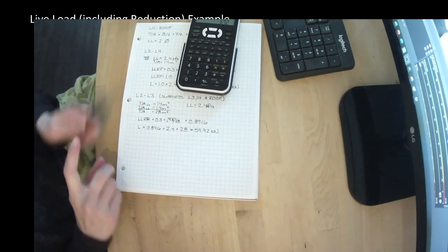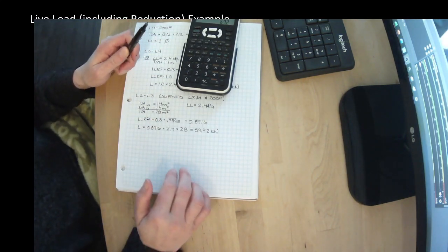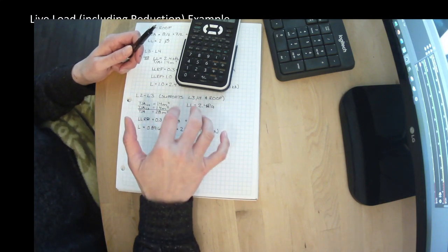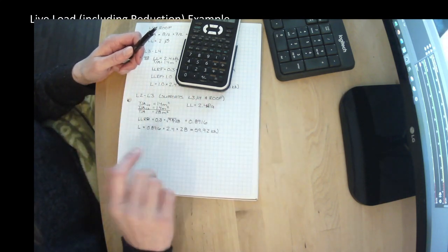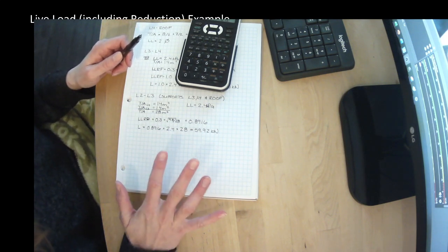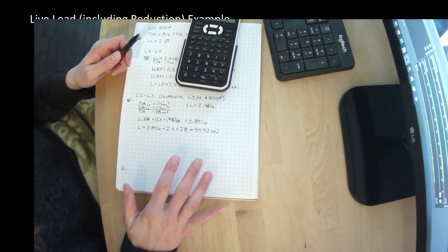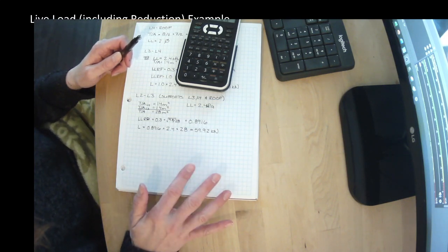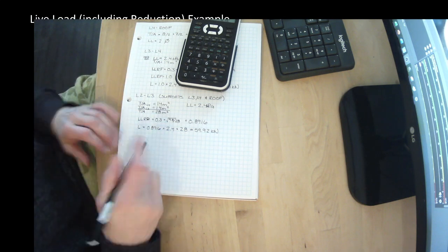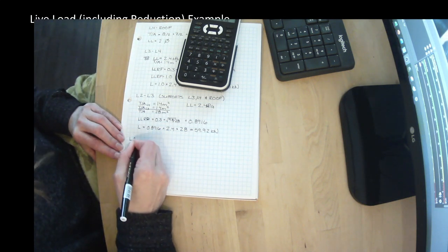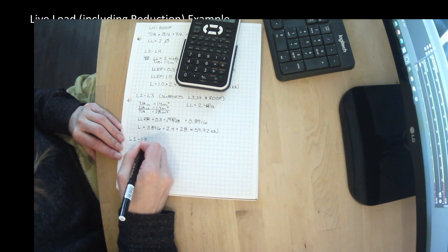What we're saying here is that the odds of both level 3 and level 4 in that zone having full 2.4 kPa live load is statistically improbable. Maybe they'd be highly loaded, but the odds of them both being fully loaded is low. Let's take a look at our column from level 1 to level 2.